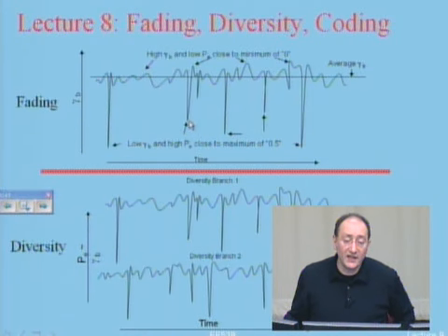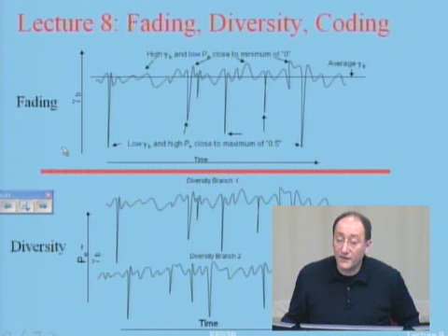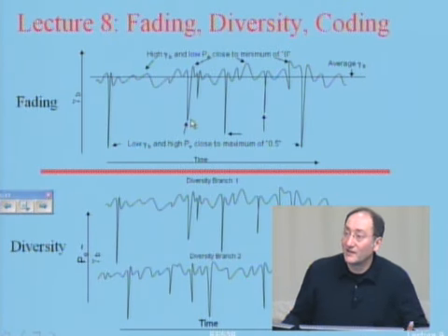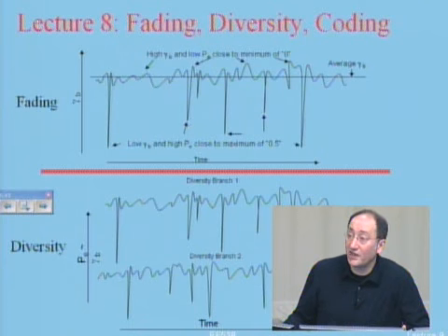And we observed that last time, because of this phenomenon, which happens like 10% of the time, my error rate goes way, way high. And the only way to avoid the error rate is to take this average signal-to-noise ratio and boost it up like 30 dB, 1,000 times. That's the only way to avoid the fade. Okay, and that's a lot of things.